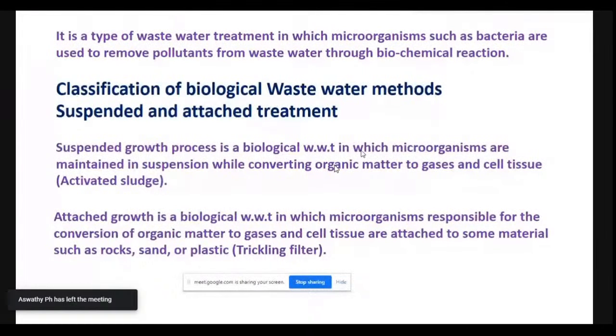So what I said now is the biological treatment. This is what you will see. The suspended growth will maintain the organisms and the solids in suspension, and then they come in contact with this. All right. And the process that is happening here will help convert this waste, or the solids, into what we call the activated sludge. Now, why do we call it activated sludge? This sludge is basically with the microorganisms, which are the aerobic bacteria, which come out as a part of the